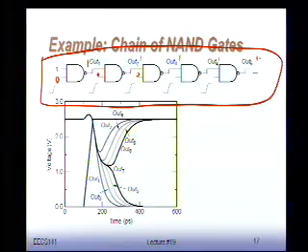And then what I'm doing is simultaneously change all the second inputs of the NAND gates to 1. And the expected result now is that there should be a 1, 0, 1, 0, 1, 0 pattern. But what you see is that initially, all the outputs start to actually change downwards, because they still see a 1 here. You change this to 1, 1 to 1. Oh, NAND gate says 1, 1, I have to go to 0. So all these NAND gates in the whole chain all start to go down.